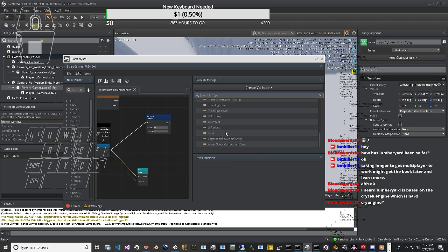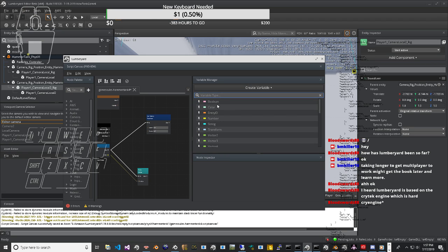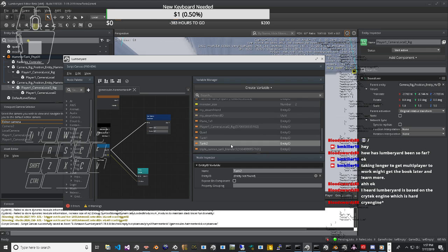As with ROAD, there is one instance per wheel. WHE is centered at the wheel hub. Under normal rolling, the coordinates of its origin in ROAD are WRI equals 0, 0, RI, where RI is the loaded radius of the tire wheel combination. Pedantically, RI should be corrected for elevation and banking, but such corrections would be small for ordinary angles. It seems not to be standard practice. I can find no reference to it in my sources.